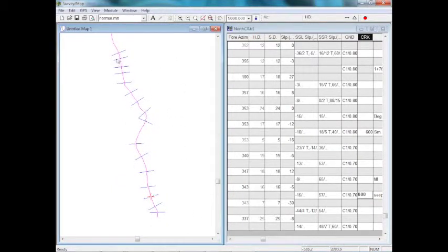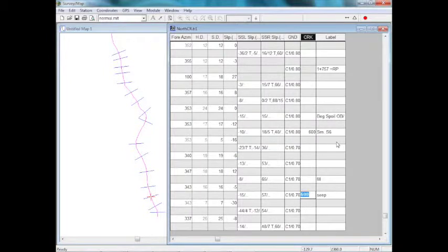You can see your traverse growing as you enter your notes, and those blue things are culverts. So this is for low volume, simple paper note survey, or using our handheld in the field. It's a Windows CE handheld device. And now that I've got this information, I can actually generate a surface from this, or I can go right into the location module and build a road on it.